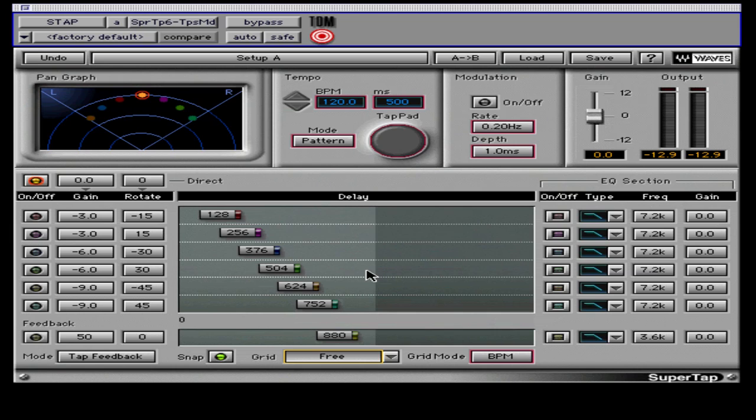Native applications will only show instances with modulation, and maximum delay time may vary from application to application. The included modulation parameters can be used to create chorus, flange, and other time-based effects. Multi-tap uses only frequency-based modulation to create special effects. A low-frequency oscillator of 20 Hz or below provides only a slight change in the delay time of each of the taps. This produces changes in the pitch of each output and is ideal for creating a chorusing effect.